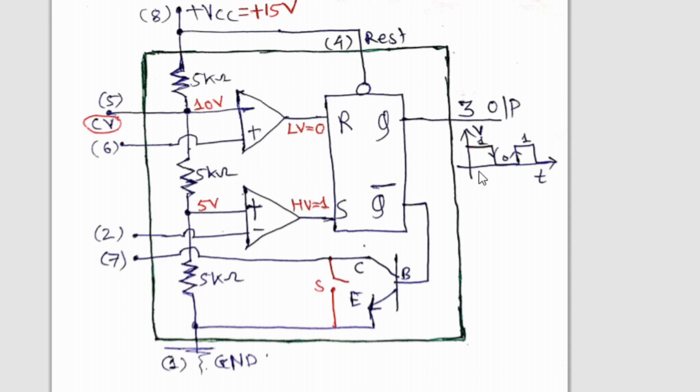Square wave is nothing but logic 1, that is a high voltage level for some time. Thereafter it is coming down, that's why downgoing arrow. Then it remains in logic 0. Then after some time again it goes up and then again remains in logic 1. So in this way, neither logic 1 is present nor logic 0, and that's called square wave, and it is the output of astable multivibrator.